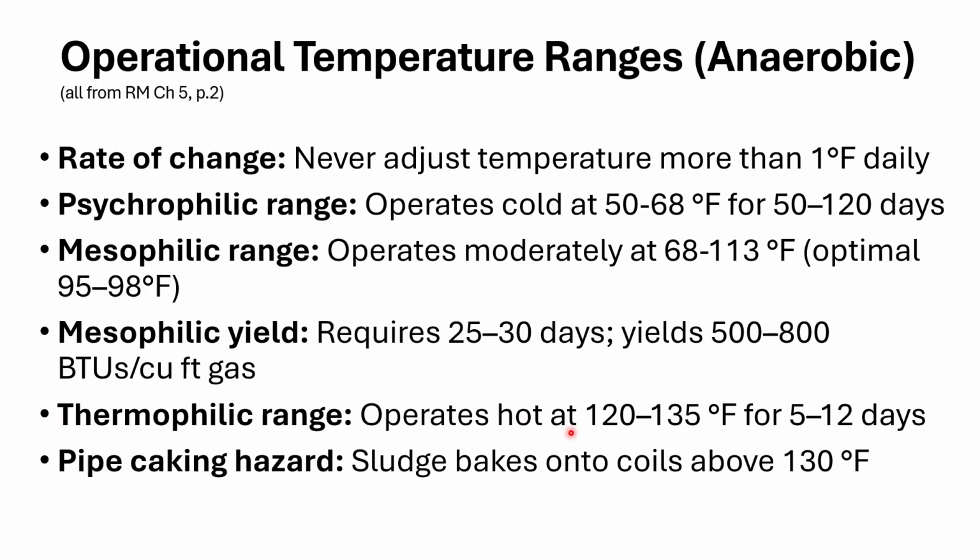The thermophilic digesters are going to run pretty hot, and they're going to digest those complex organics in 5 to 12 days. Here's the thing though, they're not going to produce anywhere near the methane you're going to need for cogeneration. Plus, it's going to take energy to keep these microbes comfortable in the anaerobic digester, okay? But it's a very efficient digestive process to concentrate our solids, okay?